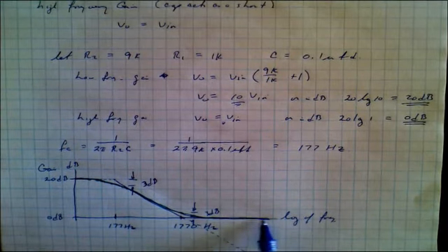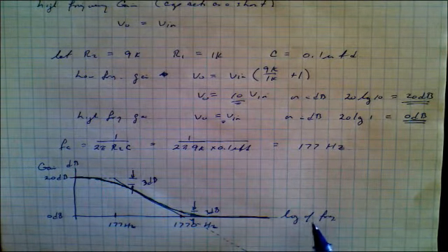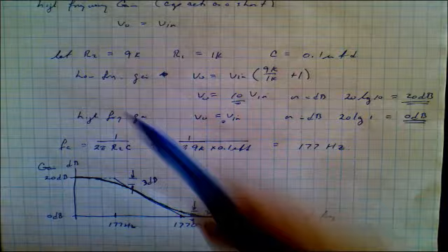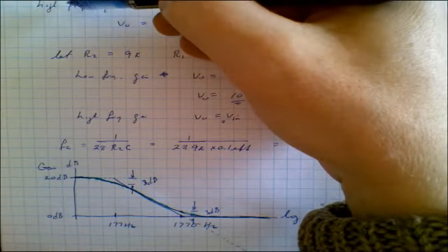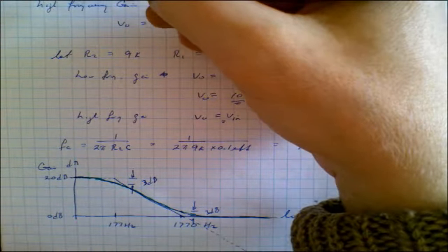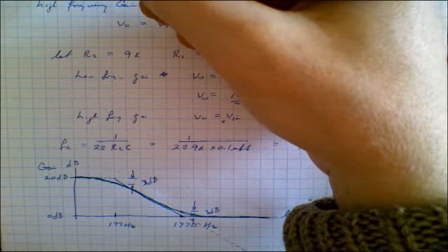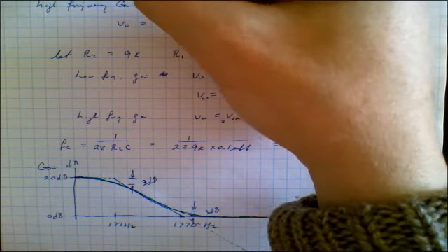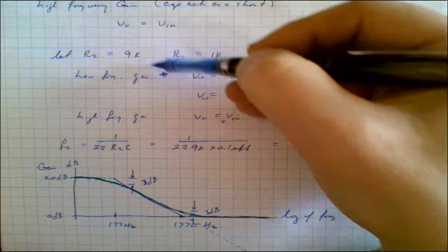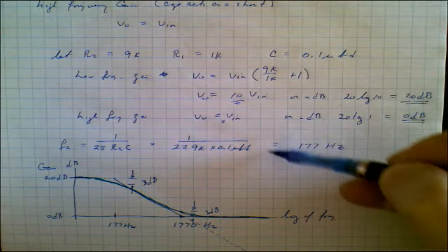So you might wonder, does it continue like this forever? Well, the answer is no. Remember that the op-amp itself has intrinsically very high gain up here, something like 80 dB, or just tremendous gains, 100 dB, 120 dB, and it has an intrinsic roll-off. It rolls off like this as well.